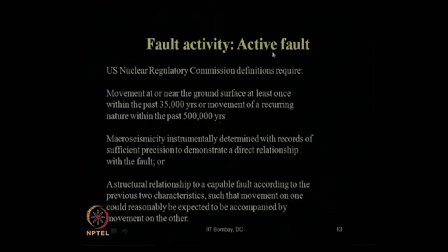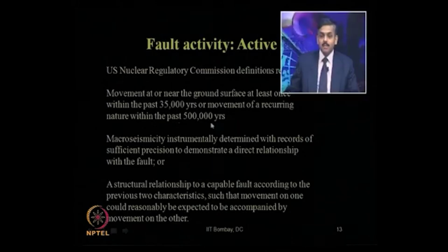That means most of the faults you will get are nothing but active faults, because this period is within the human era of what we consider as years of civilization. We have to consider almost all identified faults as active faults, as per this US Nuclear Regulatory Commission.